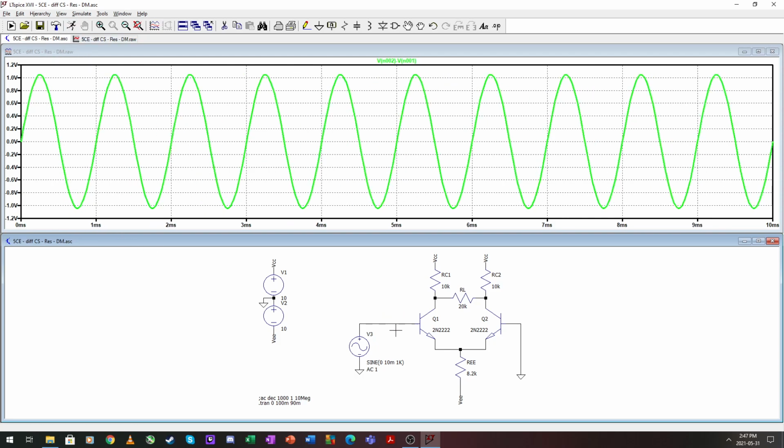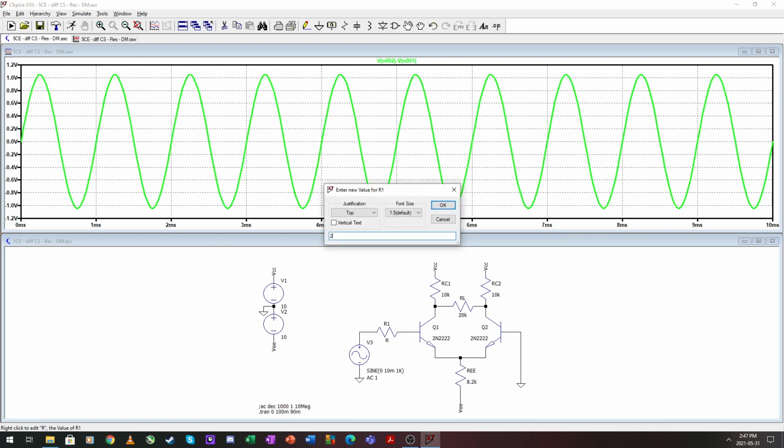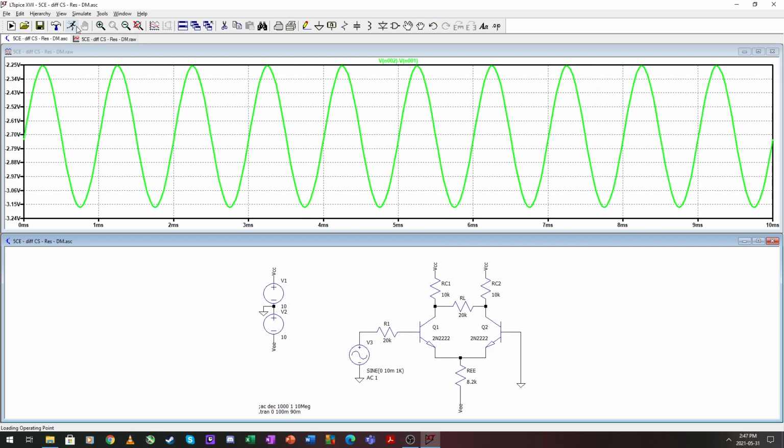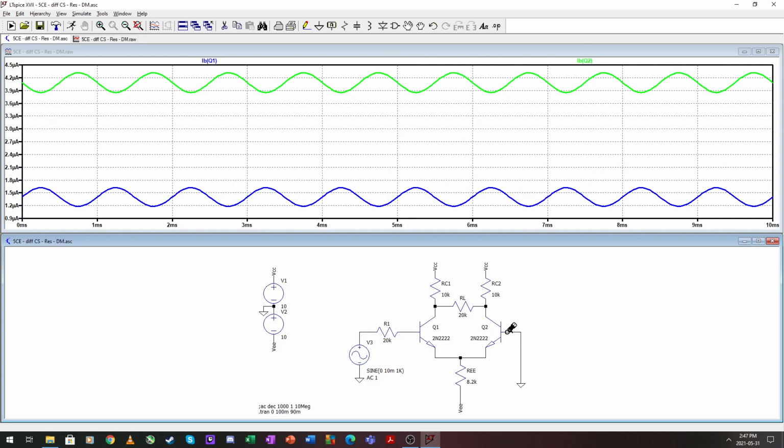And our input impedance was calculated for this to be about 20 kilo ohms. So I place a resistor here and make it 20 Ks. We have a problem. Due to the nature of our amplifiers having bias currents that need to enter, having the resistor on just one side like this will cause a problem for us.